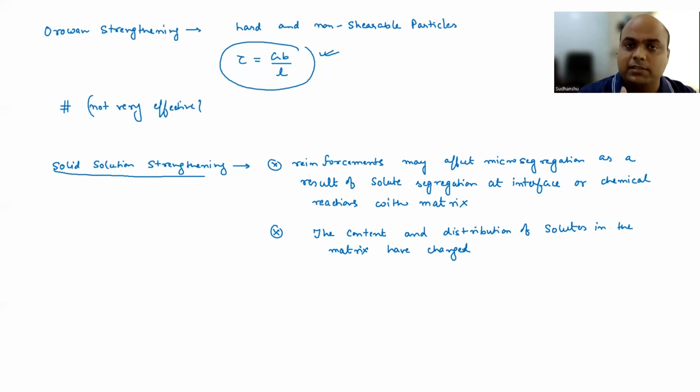Okay. So we have discussed all different types of indirect strengthening mechanisms, right? Starting from quench strengthening to work hardening to grain boundary strengthening, Orowan strengthening, solution strengthening. So the main ones are quench hardening and work hardening. They are the most important indirect strengthening as far as discontinuous reinforced particulate metal matrix composites are concerned. Precipitation strengthening is also important if the matrix can show precipitation strengthening, right? Orowan strengthening is not that significant because the particle size is slightly higher, but it can give some strengthening if the particle size is reduced dramatically.